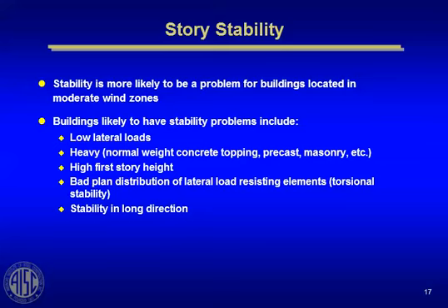Therefore, it's a pretty soft building, stiffness-wise, in the lateral direction. At the same time, you have a large P, a lot of gravity load. Well, a large P and a low lateral stiffness produces a potential story stability problem if you look at what controls story stiffness. And it's basically the gravity load on the story and the stiffness of the story.